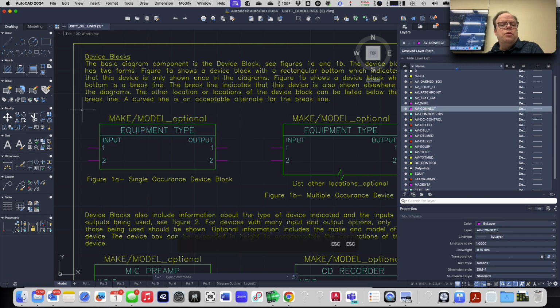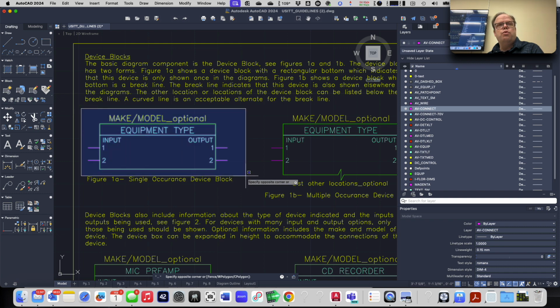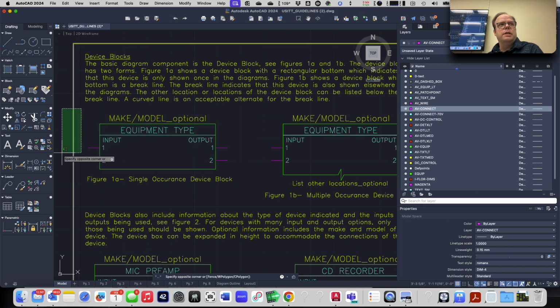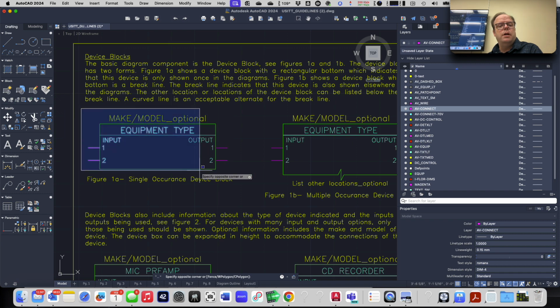Remember when we learned about selecting: you basically click, release, and then you can either drag right and it turns blue, or you can drag left and it turns green. If you go right, the blue means it'll only select everything that is completely contained inside that box. If you go left, it will select anything that is even partially contained inside the box. So see here, it's going to select that border, even though I haven't dragged all the way around that whole border. But if I go here, it only selects the things that completely fit inside of there. So it's not going to get the U. Right. From where you were at. Okay. Yep. And then right click to. No, left click again. Stop.